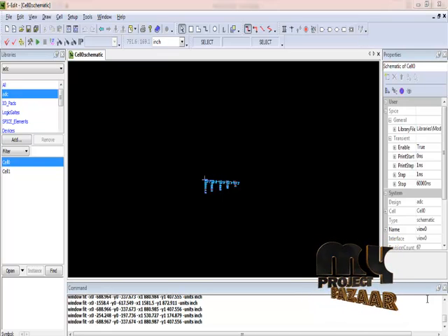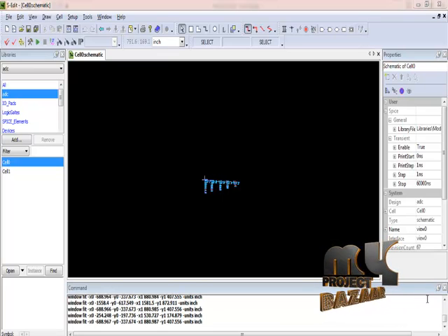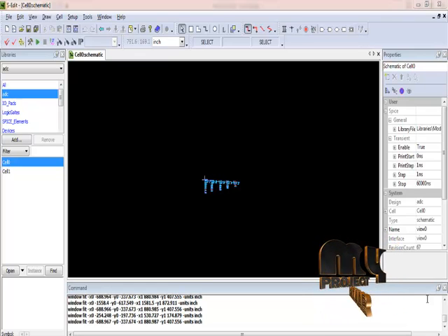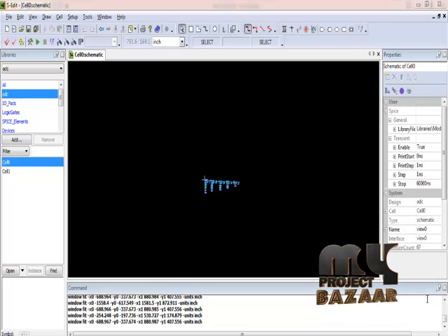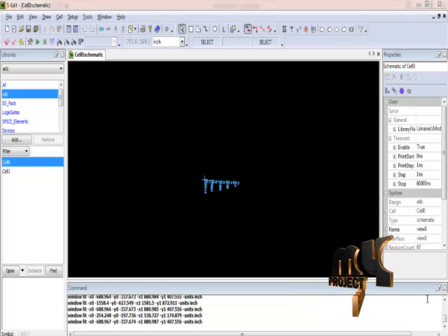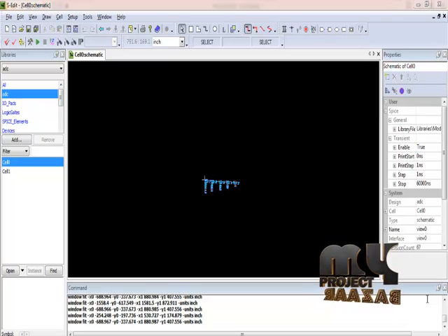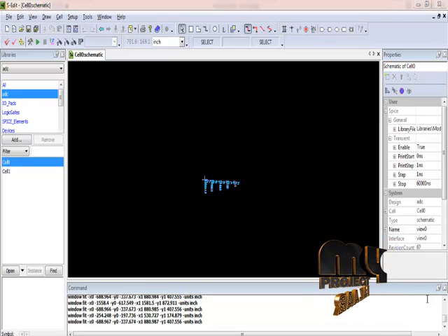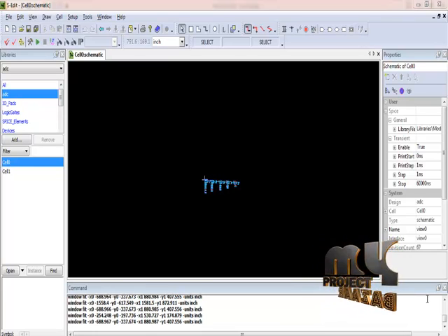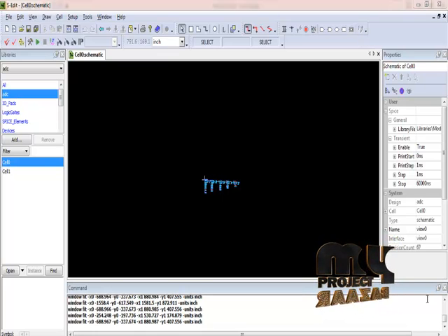We have implemented the design circuit in Tanner EDA version 13. We have used the S-Edit process. We first created a cell. After the cell was completed, we designed each and every part, using the PMOS and NMOS transistors. Here we are connecting the PMOS and NMOS. We considered the CMOS process, and then we created the control process, the read and write bit of the process.